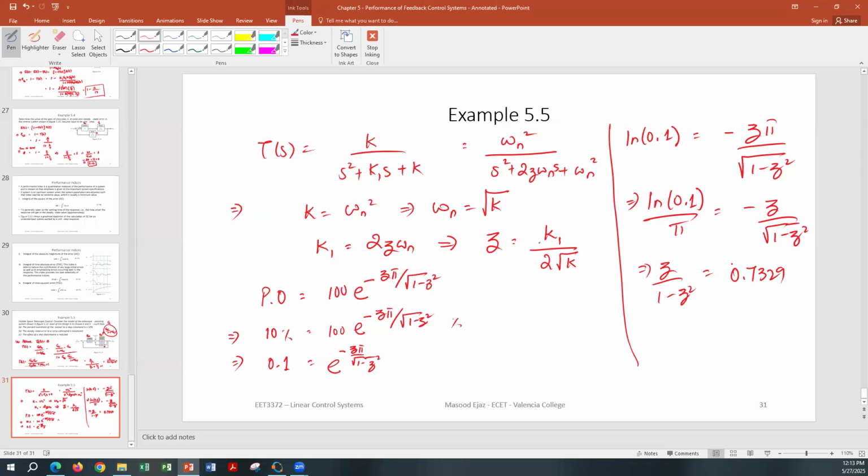You cannot just use this expression as the peak overshoot expression. You're going to calculate the transfer function and the response, and then plot the step response. You can still plot the step response without calculating the time domain expression using the step function in MATLAB, but you cannot use the equations. These equations are specifically for the second order system only.